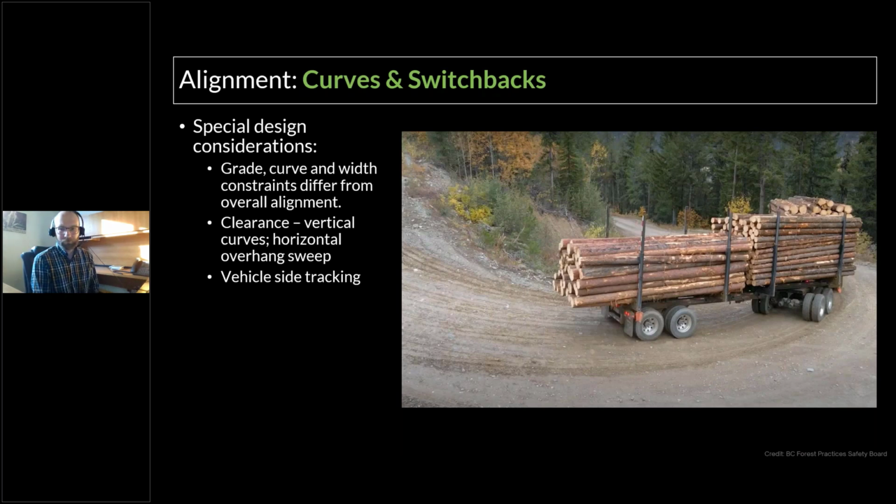This is kind of common knowledge for anyone that's designed a switchback, but if you haven't, just think about it. If you're on one aspect, you turn directly into the hill, well, you're going to increase your cut to stay at your design grade. And then you want to make sure that you have the topographic relief so you actually get out of that cut and you don't just have this big trench going up the hill because you didn't lose that cut. If you have that big trench, it's not going to be ideal. You're going to increase your disturbance areas, construction emissions, and your costs are going to skyrocket, so no one's going to be happy.